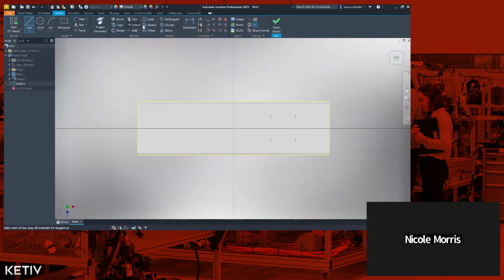Then create a construction line diagonal because the measurement is diagonal. Okay, so the first thing I'm going to do is add my dimension. I have to switch this to diagonal, 5.85. And then I can start to go in here and add some of my other dimensions, 4.8 from the top, 1.97.